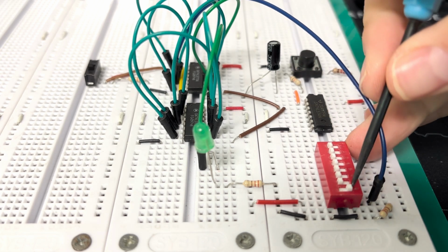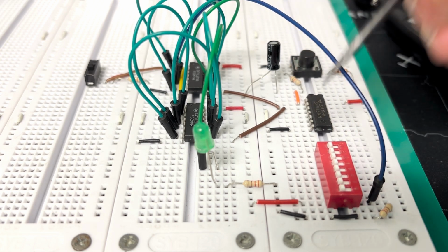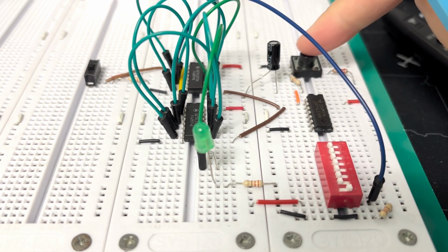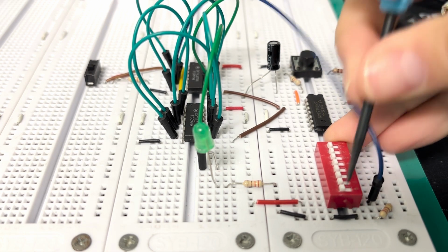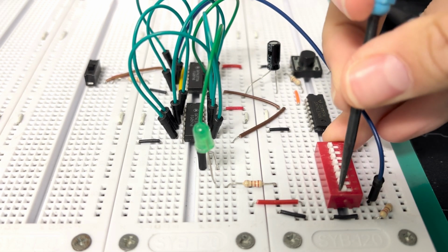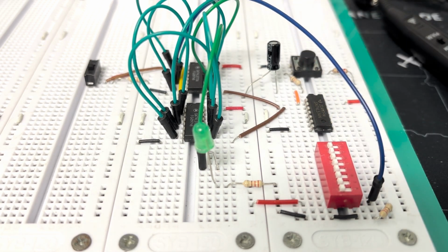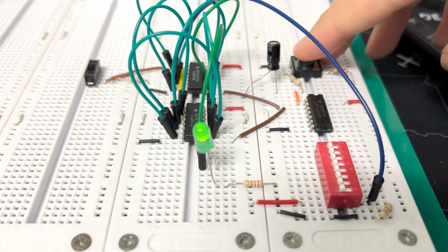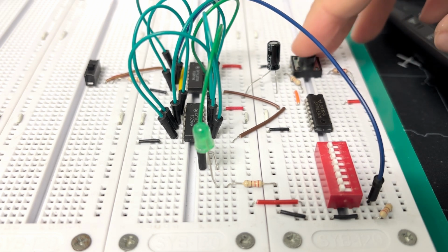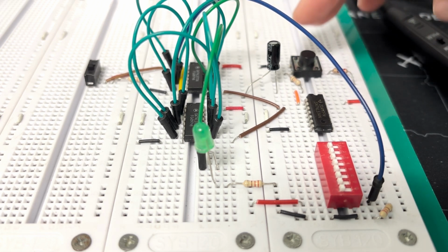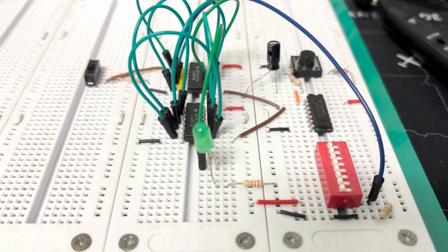0x6A into the register. I use a push button to clock data into the register. Because the flip-flops were initially cleared out, the output, displayed on an LED, appears off for the 8 clock cycles where data is shifted in. The output data then appears one bit at a time on the next 8 clock cycles where I push the button to shift data back out again.